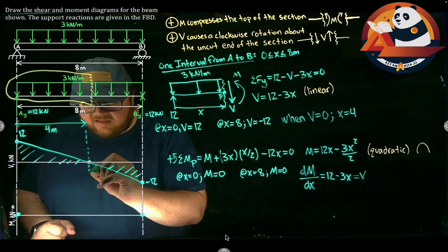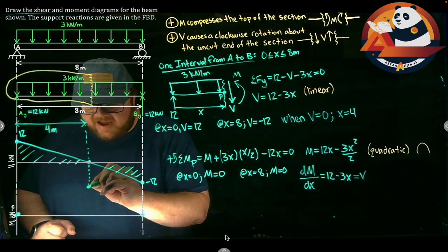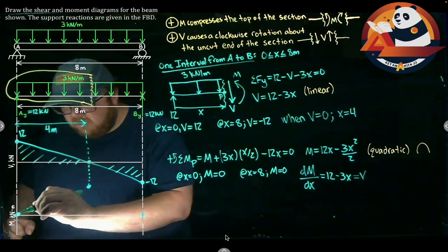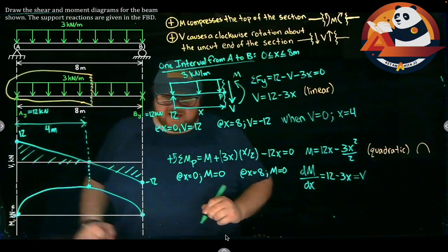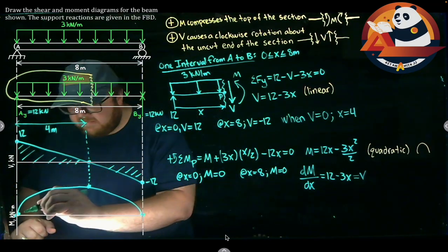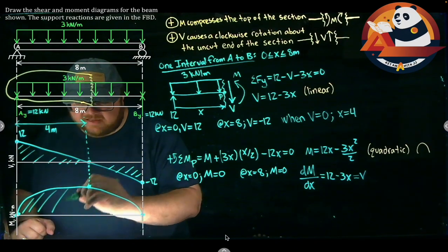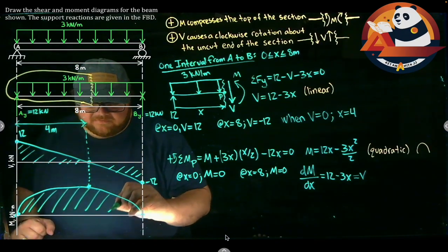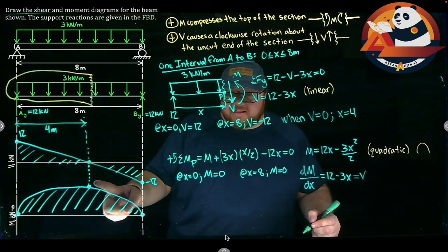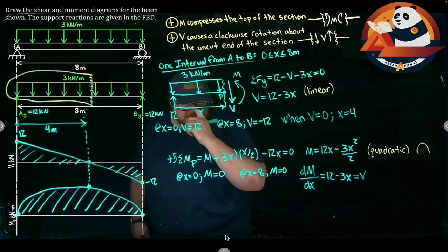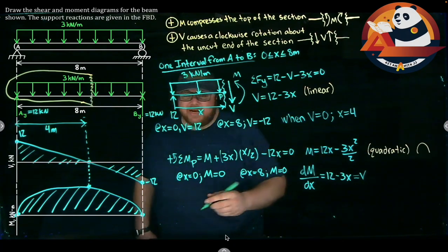That should directly correspond to a maximum moment in here. That our moment should parabolically increase up and come right back down. We're not going to worry that my scale's a little bit off here. That should be right in the middle of everything. 4 meters from either edge. But we know we're going to increase up to that max point. I just need to find that. That's going to be one last critical point in here.